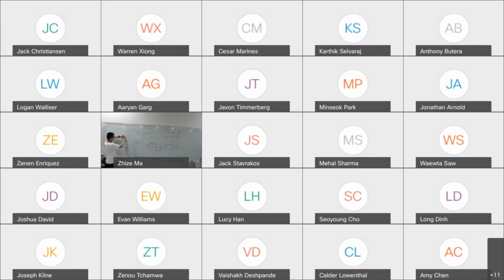From here to here, that's 1 period. So for example, here it is 100, so the frequency is 100 hertz. So the period is 1 over 100. That's 10 milliseconds. If here is 1,000, 1 over 1,000 will be 1 millisecond.